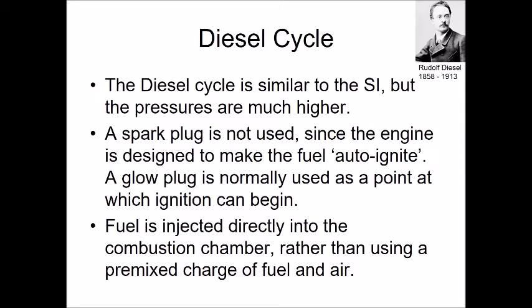So if we take diesel fuel and we squash it hard enough, it will start to burn. I don't need a spark. Now, we quite often have something called a glow plug in a diesel engine, and a glow plug is actually just a hot surface where we would like the combustion to start from, but it's not a periodic thing like a spark plug. We don't hit it with a spark every now and then when we want the combustion. We auto-ignite the combustion via compression, but we'd like it to start in the same point every time. It makes the engine run a bit smoother, really.